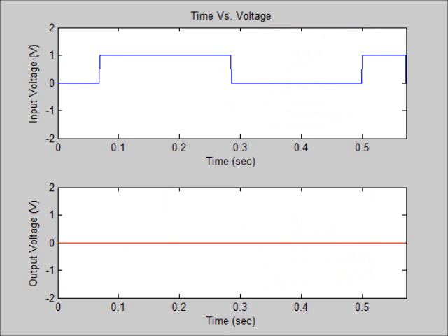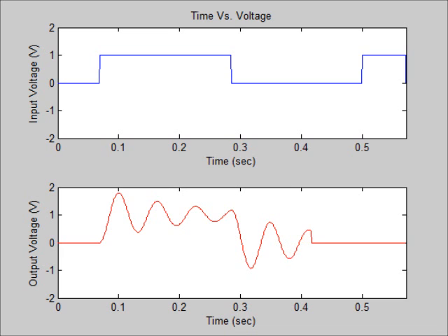So the electrical example is pretty similar to the mechanical example in that it resonates way past the input voltage of 1 volt, and then it continued to resonate for much longer than it did in the previous case. And then this happens again when the step function goes back down to 0. So the resonance is the highest when the damping is low.